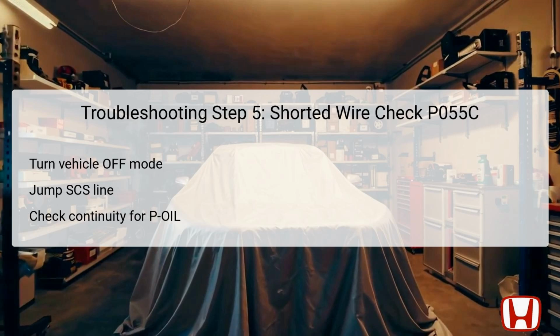If continuity exists, it reveals a short has occurred, necessitating repairs to the P-oil wire, which connects back to the PCM. If no continuity is found, further checks for service information regarding the DTC or replacement of the PCM may be warranted.